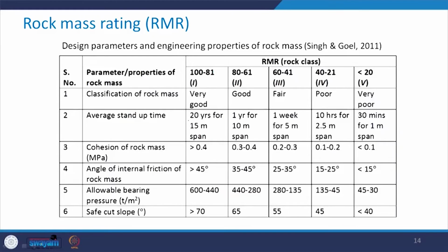See here, as I explained, it is 20 years for 15 meter span. It should not be that we wait for 5 years to provide the support system because the stand up time is this large. No, as soon as we excavate and it is convenient from the point of view of the construction activity, immediately we should provide the necessary support system.